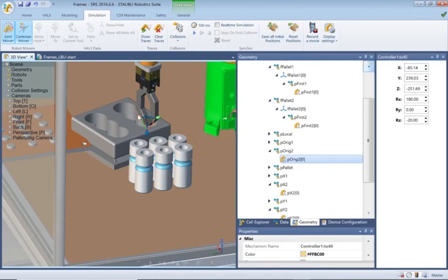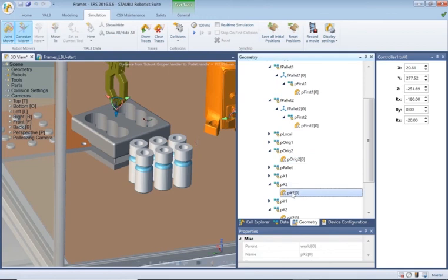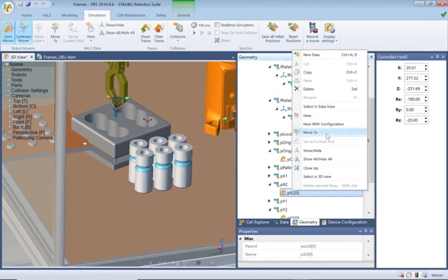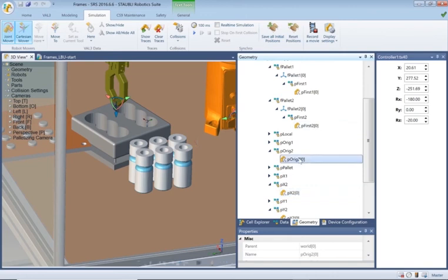What you can do is grab the icon here and just slide it along, so you can see it's actually going along the x-axis, which is really very helpful. So let's move it along the x-axis, and that we know is X2. Right click here with configuration. Let's go back to the origin.